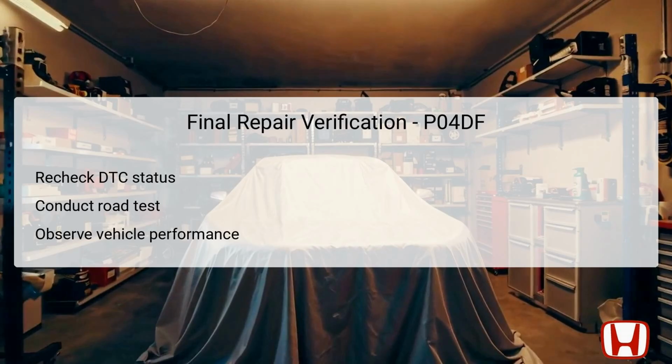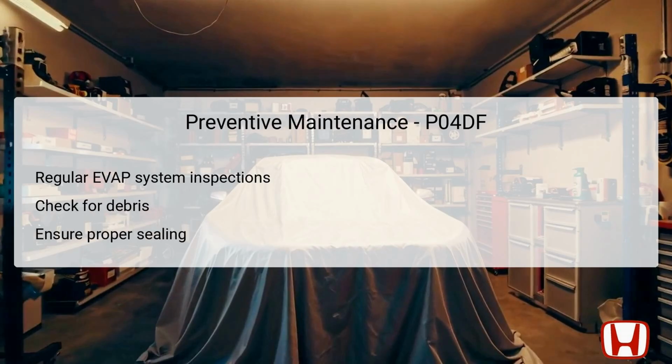Successful resolution of the DTC P04DF will reflect in both the absence of the error code and improvements in vehicle function. To prevent future occurrences of DTC P04DF, regular maintenance of the EVAP system is crucial. Schedule periodic inspections of the EVAP system to ensure all components are functioning correctly and are free of blockages or debris. This practice enhances the longevity and efficiency of the system, ultimately preventing excessive emissions.